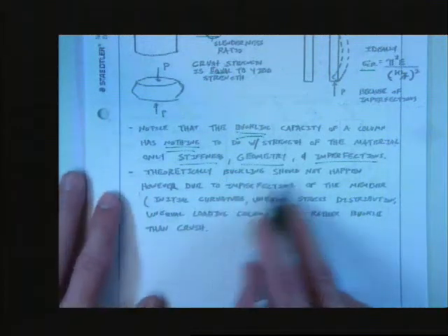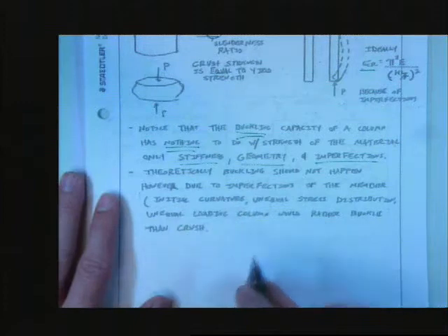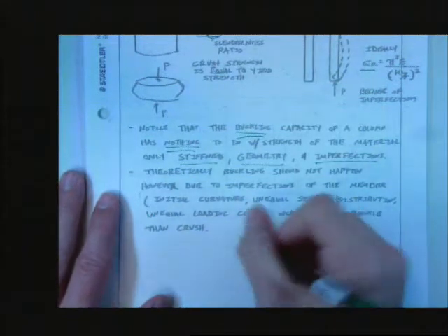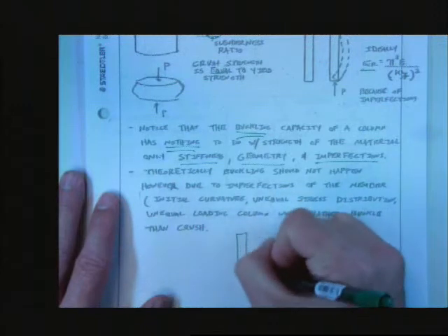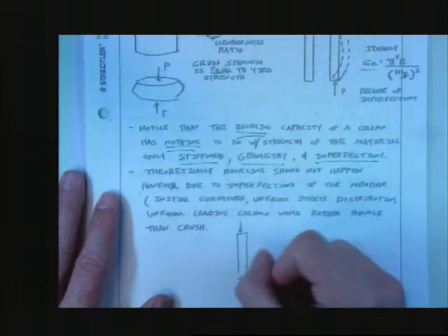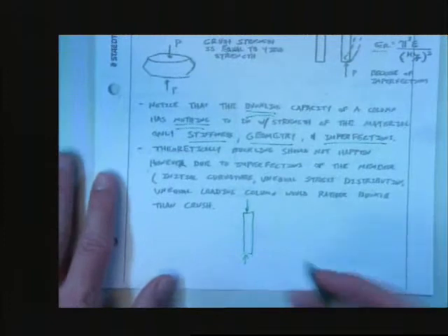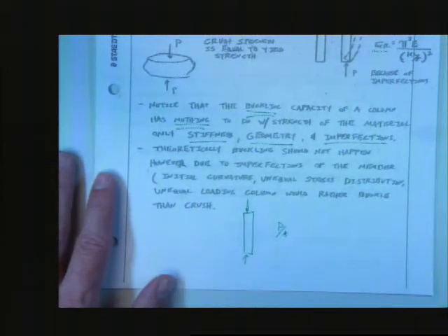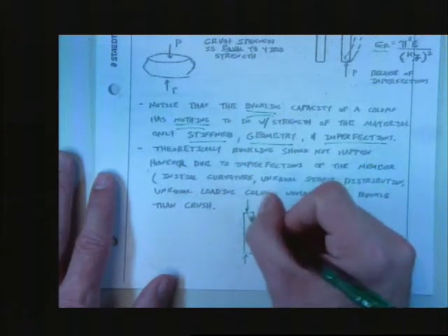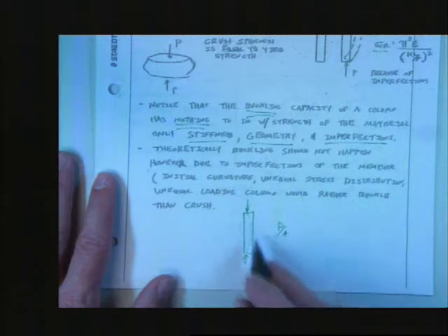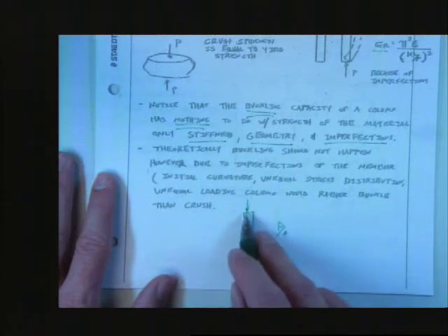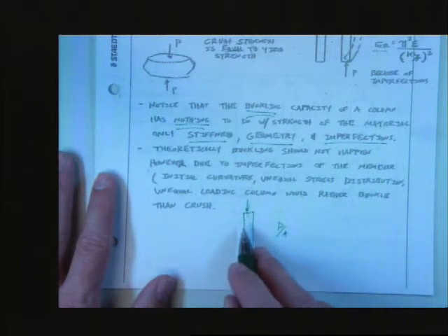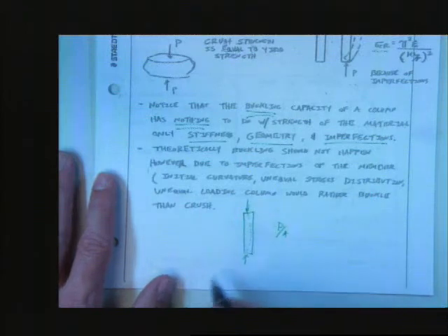Theoretically, buckling actually should not happen. If you talk about it purely mathematically, you start to load a member up and you put loads in the center of it. What's the stress? It's P over A, right? It's P over A forever, right? Well, what happens is that there's a thing called imperfections. Either imperfection in the length, an imperfection in the loading, an imperfection in the material, and the thing starts to bend a little bit.